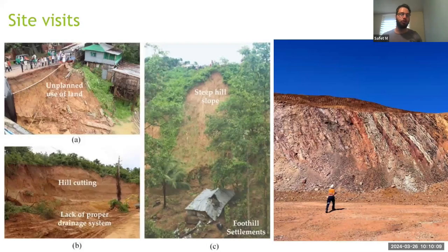And one really important thing, which I would suggest doing before sending the offer for geotechnical design, is a site visit. If you do the desk study, you're going to have a lot of knowledge before going to site, but on site is where you can see what reality is.